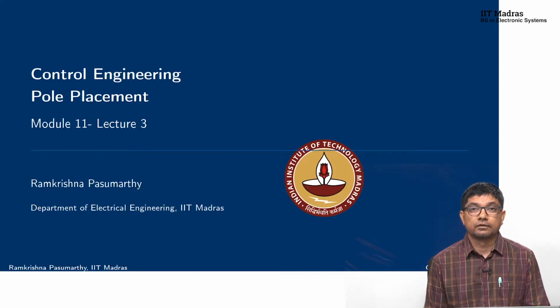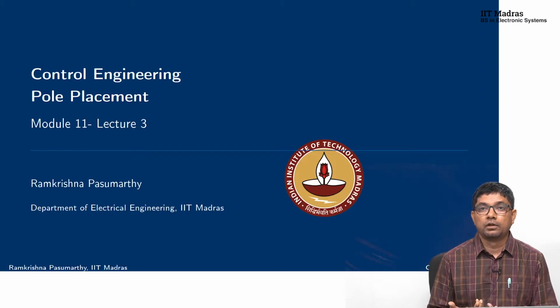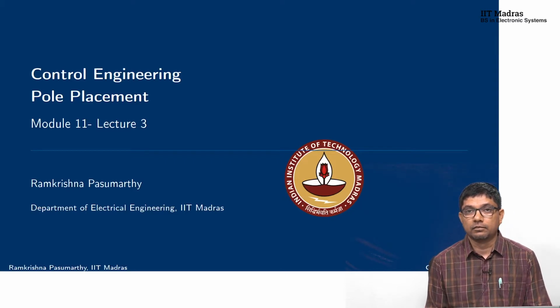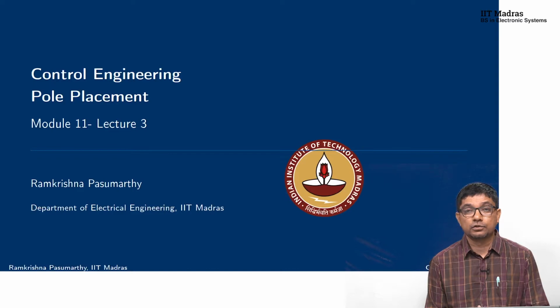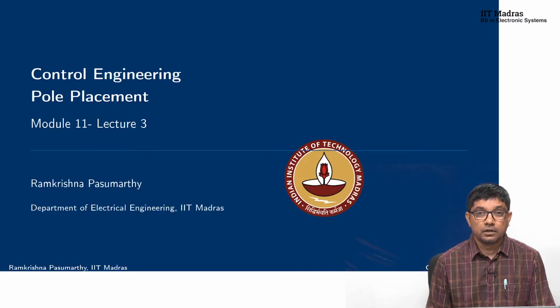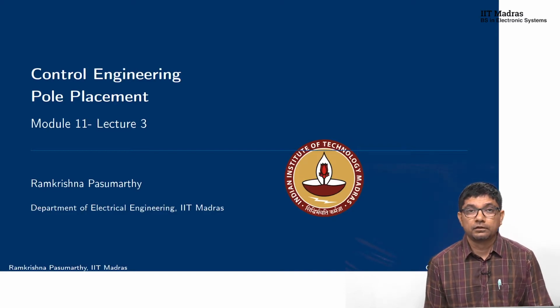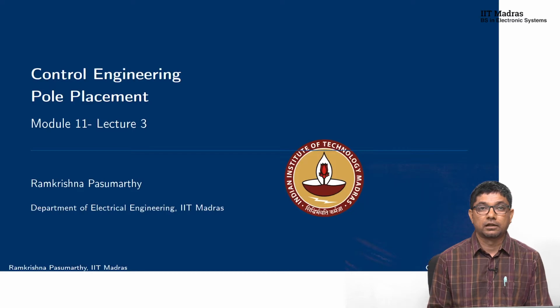What we saw was when the system is uncontrollable, there is a pole zero cancellation, where the uncontrollable pole gets cancelled by a zero, which means I am unable to control that pole. The transfer function therefore shows me only those poles. The transfer function carries information of only those poles which are controllable. Okay, so what can we do with the systems that are controllable?